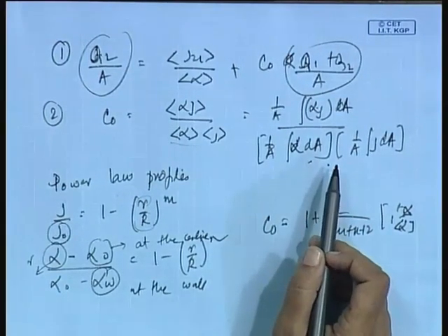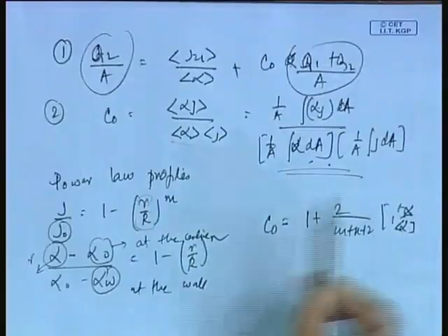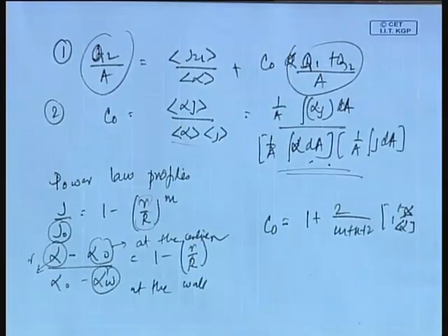There are two particular cases. One is when there is a heat flux and intense vaporization at the walls, so there is a larger vapor concentration at the walls as compared to the center. The other is when we are introducing air through, say, a porous wall. Then, in the developing region, there is greater concentration of air bubbles at the wall as compared to the center. For such cases, we cannot use the C0 values which I have written down in my PPT. They are mostly for fully developed flow cases or for those cases which have a convex sort of profile. So, for anything else, C0 has to be derived from the basic equation which I have written down.